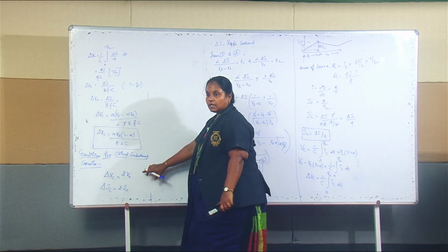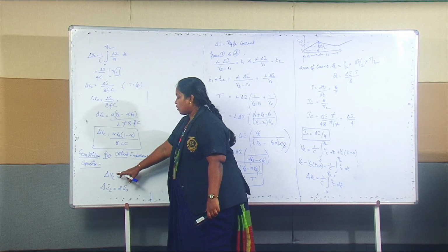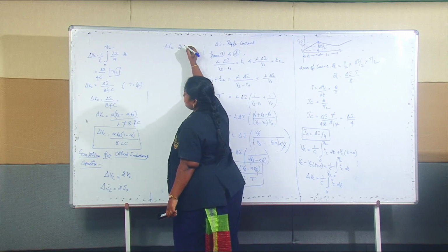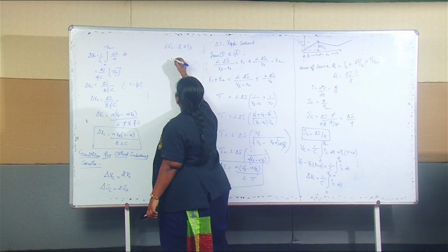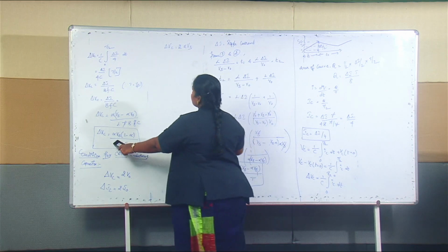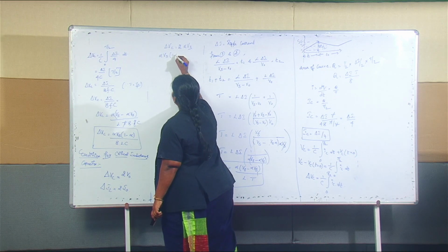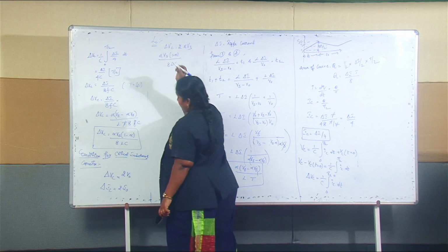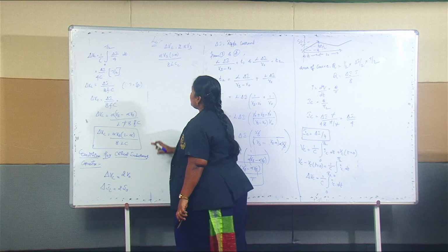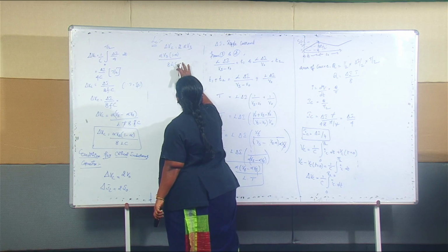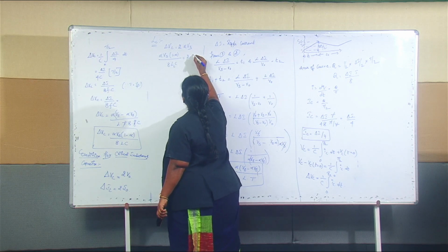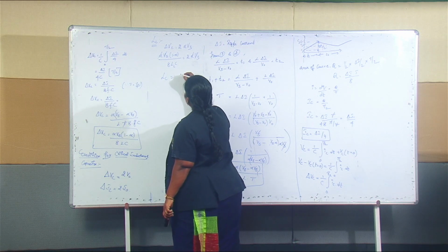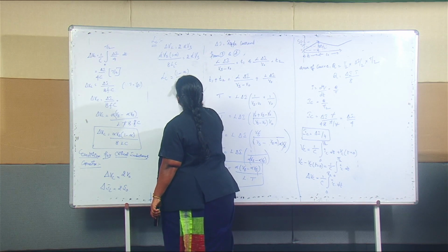We have considered the critical condition: del Vc should be equal to 2 times V naught. So del Vc is equal to 2 times V naught, which is 2 alpha Vs. Del Vc is alpha Vs (1 minus alpha) by 8 L C. When del Vc is equal to 2 V naught, L will become Lc, equal to 2 times alpha Vs. This alpha and Vs will cancel each other. So Lc is equal to (1 minus alpha) by 16 C.